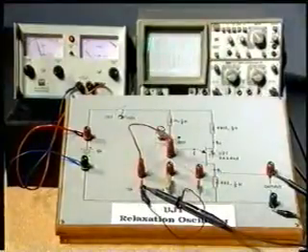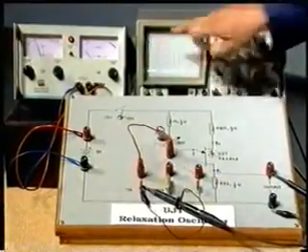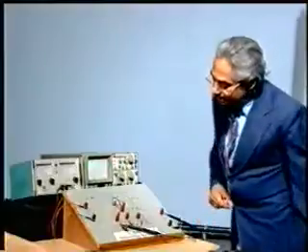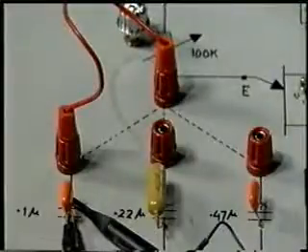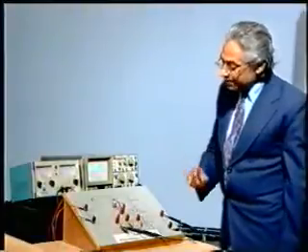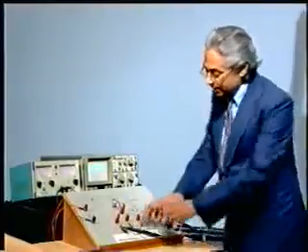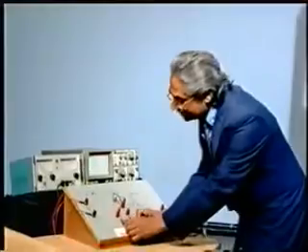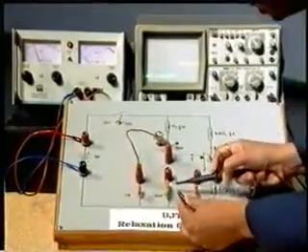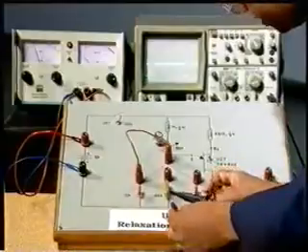Okay, the output, this is the charging and discharging of the capacitor, and below, the second trace you are seeing is the output pulses across this capacitor, which is 0.1 microfarad now. Now I am not going to change the potentiometer, but I am going to vary the capacitor because I have a provision here. So I will place it across the second capacitor now. Let me place it across this 0.22 microfarad now.